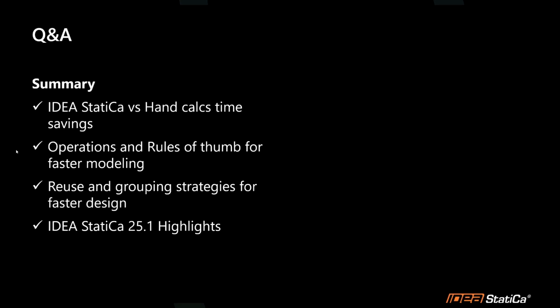So although you may not get those checks, you will see those as part of the results. So if you have a connection that is low in stiffness, you will see a failure maybe due to those prying actions presenting higher forces than the regular bolt forces. That's right. Yeah, we just are checking it inherently in a different way there.